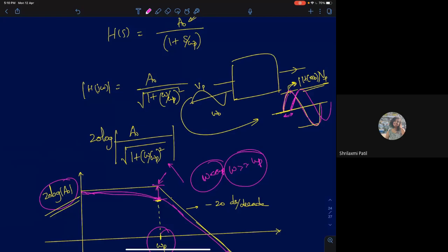Now, what use does phase response have? It's a good indicator of non-linearity of a system. We haven't spoken about phase distortion and all of that. Generally, it's a topic reserved for filters. But from a circuit design point of view, phase response becomes very important, especially when we are talking about systems with feedback. So that's why it's very important to understand the phase response of a system.